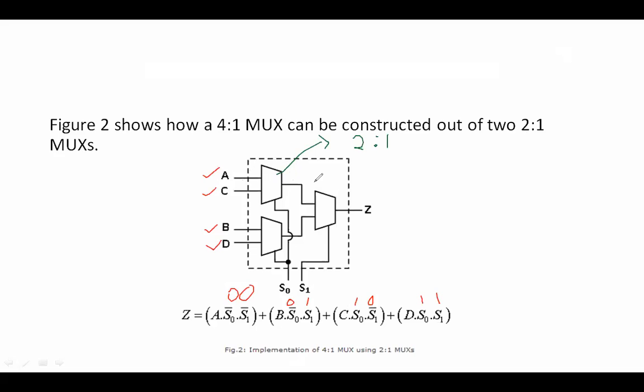So I can also think of this as getting converted from parallel to serial. I have lines in parallel here, but I'm just getting one output. These are my parallel inputs, and the output that I'm getting is a serial output. Using one 2 is to 1, then you have another 2 is to 1 mux here. With the help of your select lines, I'll be combining them, and this is also another 2 is to 1 mux. Understood?